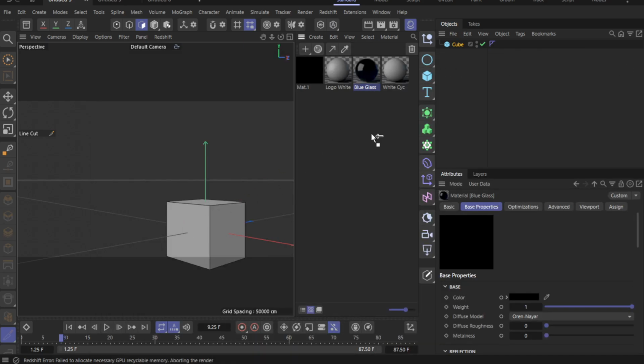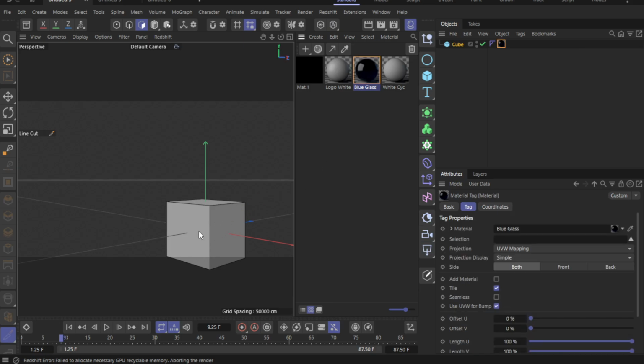If you want the screen to glow realistically, you can make the texture emit light. In the same material, copy the texture from the Color channel and paste it into the Luminance channel. This lets the surface appear self-lit in your render, which is perfect for monitors, phones, or signage. It's an optional step, but it adds a lot of believability without extra lighting.